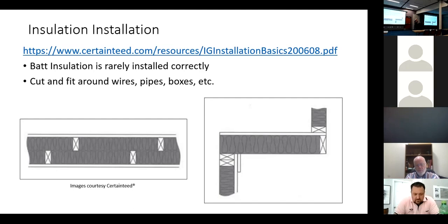So what's the temperature in the attic? It's either hot or cold. Let's say it's cold, wintertime. What's the temperature of the backside of the drywall? Well, it's closer to room temperature than attic temperature. So the air in contact or close to the backside of the sheetrock is going to rise because it's warmer than the surrounding air in the attic. As it rises, it pulls cold air from the attic up, and we get this convective flow.